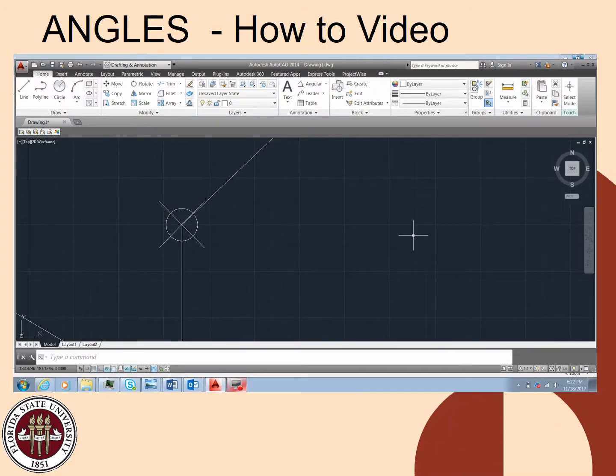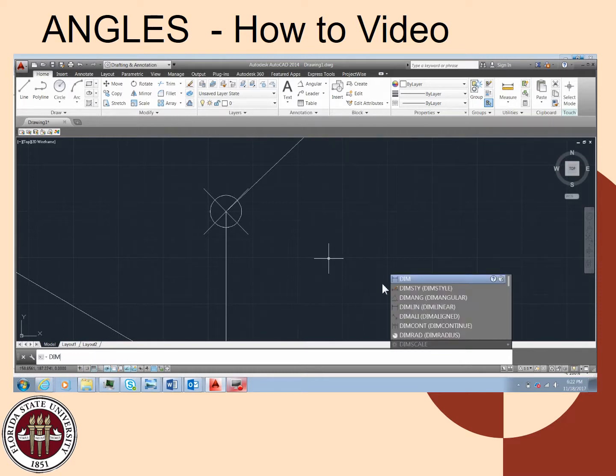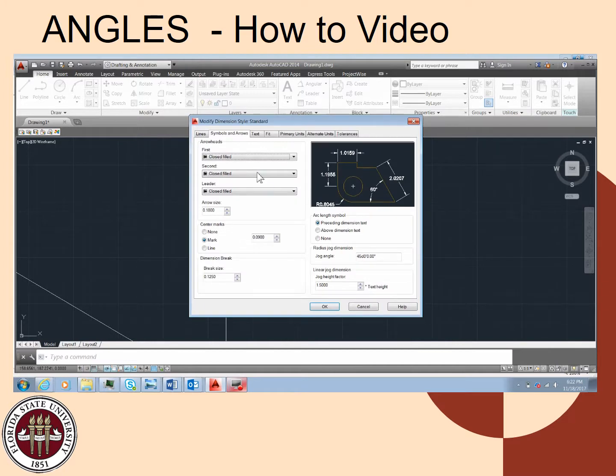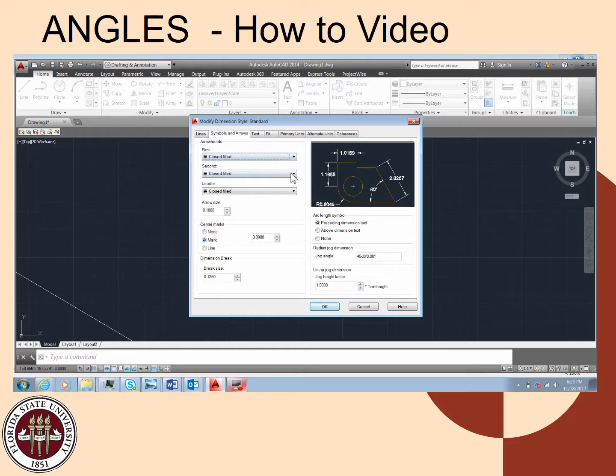I need to install my angles. Although I entered them previously, that does not tell the user anything about this particular run, it doesn't tell the length, nor does it tell the particular angle that this run was installed at. So I can go to the Dimension Style Manager, Dim Style, and I can work with the classic head and change many of the properties of it.